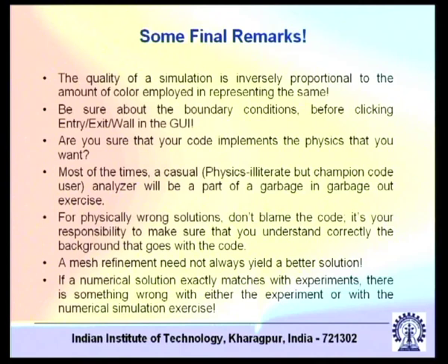Now the other thing is, when you have a solution, how do you validate it? CFD problems have benchmarks. There are some standard benchmark problems in the literature, and you can validate your solution with them. Sometimes you validate your numerical solutions with experimental results, but if a numerical solution exactly matches with experiments, there is something wrong with either the experiment or the numerical solution.